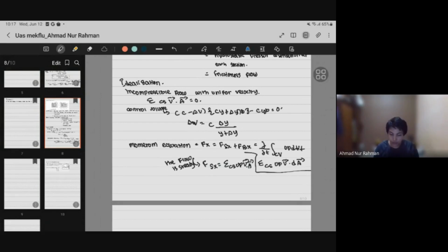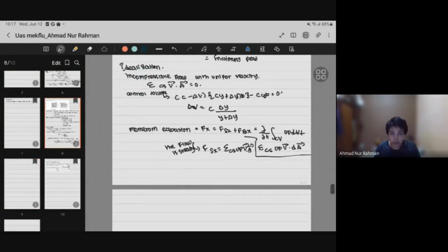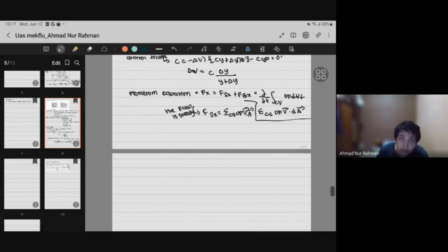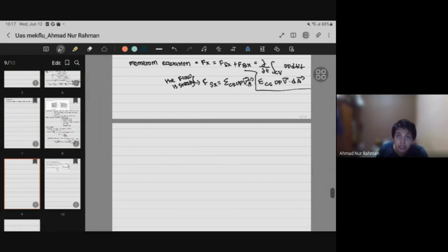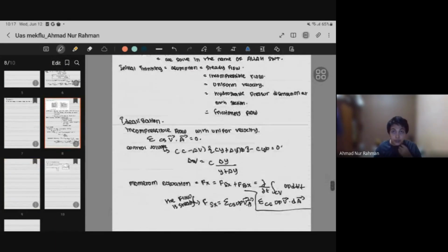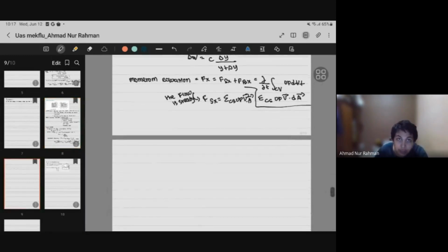And that is how you solve the problem. So the surface force consists of pressure force on the two ends by assumption 5. We neglected friction. So the gauge pressure at the two ends is hydrostatic, as illustrated in the figure above. So the hydrostatic force FR on a submerged vertical surface of area A is given by the simplest result.